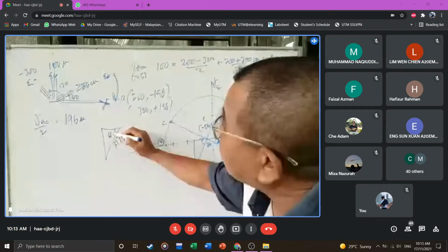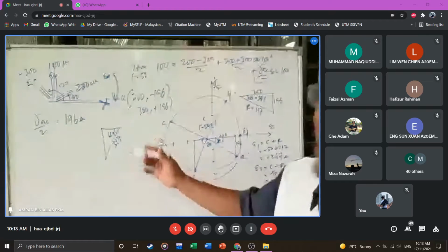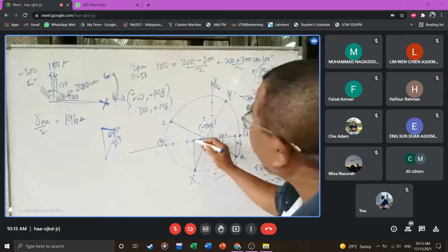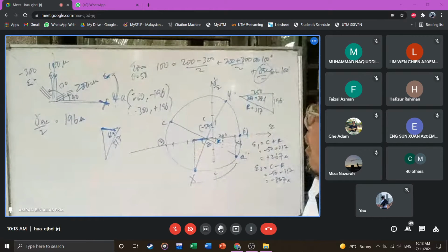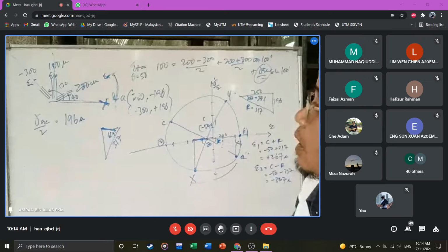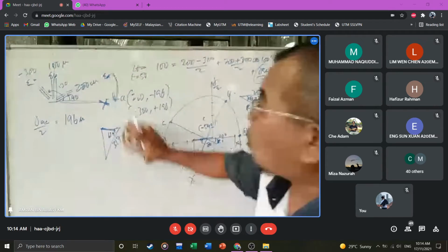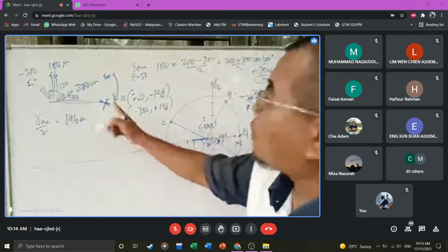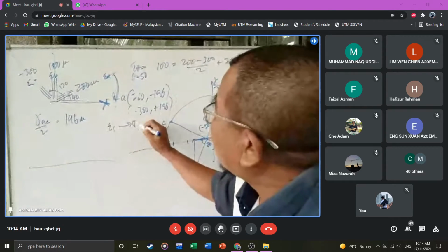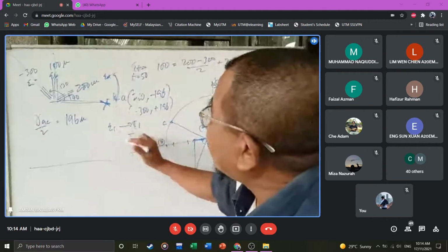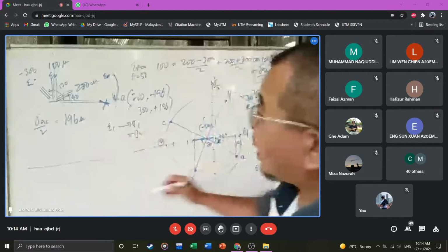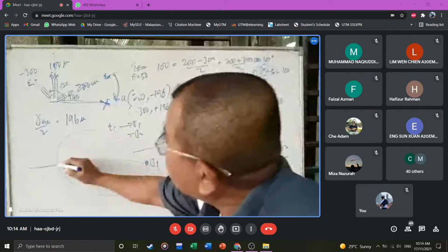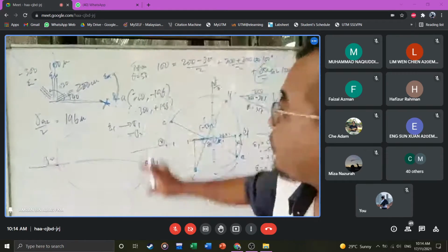61.9. Very easy. This value here, that value here, find the value. Minus 50 plus the value, you got that one. That is EX. And then, when you do this one, you find your Mohr's circle, you convert it from epsilon 1 to sigma 1 and then sigma 2 there. Then you got a Mohr's circle of sigma there. This is sigma 1. This is sigma 2. What's the value there?